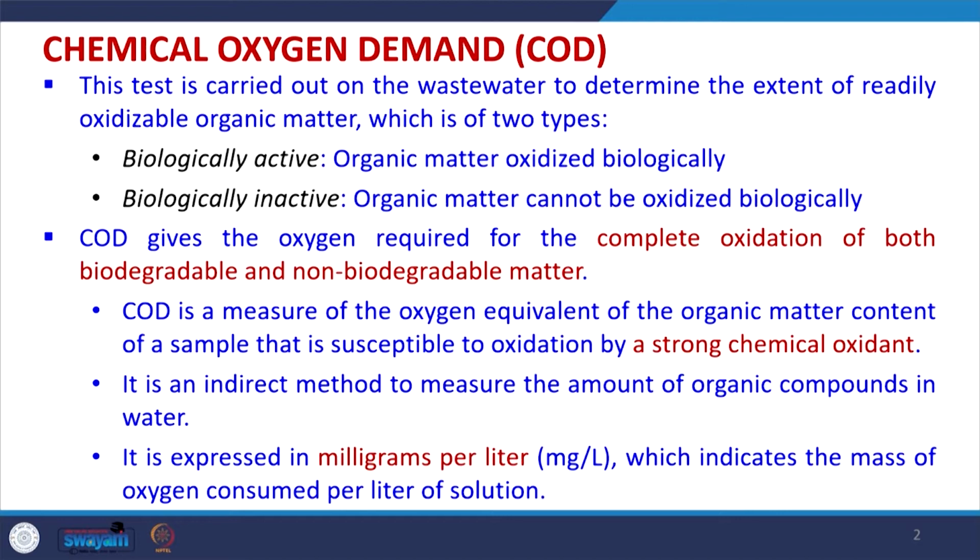Biologically active means the organic matter which can be oxidized biologically, and this can be determined using the BOD estimation method. But there may be biologically inactive organic matter which will not be oxidized by biological means. It will, but it will take a lot of time for degradation to occur, much slower than the usual scenario. So, in this case another test is used, which is called chemical oxygen demand.